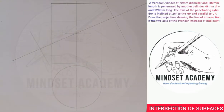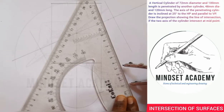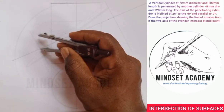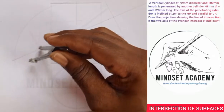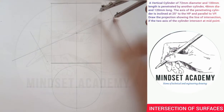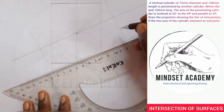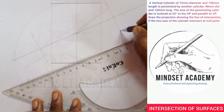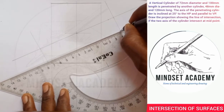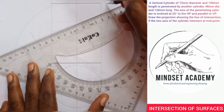Is that okay now? We're told the diameter is given as 48. That means half of it is 24. So I'm going to measure 24 on my meter rule, and I'll place it at this point. I'm going to mark 24 to this side and 24 to this point. I'll come here also, mark 24 here and also 24 here. In doing that, I can easily join them together with a faint line this way, and a faint line this way.